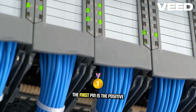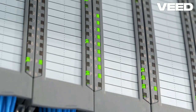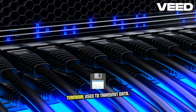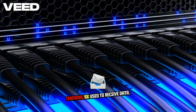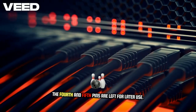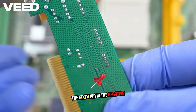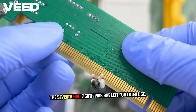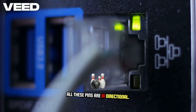The first pin is the positive terminal used to transmit data, TX+. The second pin is the negative terminal used to transmit data, TX-. The third pin is the positive terminal, RX+, used to receive data. The fourth and fifth pins are left for later use. The sixth pin is the negative terminal used to receive data, RX-. The seventh and eighth pins are left for later use. All these pins are bidirectional.